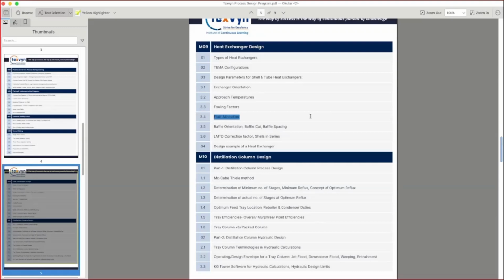For example, whether it is a fouling service or a non-fouling service, which one out of the two is a high design pressure condition and which one is a low design pressure condition, then which one has a more temperature drop, as well as what type of TEMA configuration we are choosing. So depending on corrosiveness of the fluid, fouling nature of the fluid, and the various aspects of the hot and cold side fluids, how we make a judicious choice of the fluid allocation on shell and tube sides.